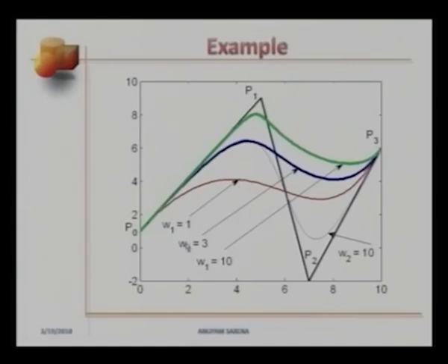With the addition of these weights, keeping the control polyline the same, I can now play with the shape of a Bezier segment by merely changing these numbers or the weights. As I increase the weight corresponding to any data point, the curve will gravitate towards that data point.